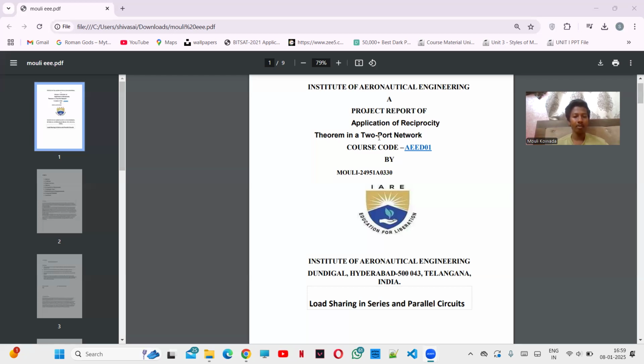In this type of circuit, the same current flows through all components since there is only one path for the flow of electrons, and the current is determined by the total resistance of the circuit and the applied voltage. The relationship is given by Ohm's law, where I is the current, V total is the total voltage, and R total is the total resistance.